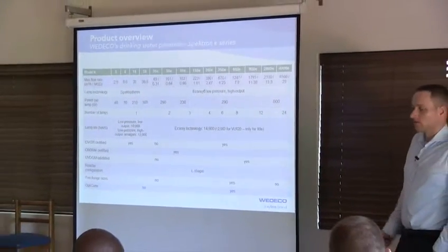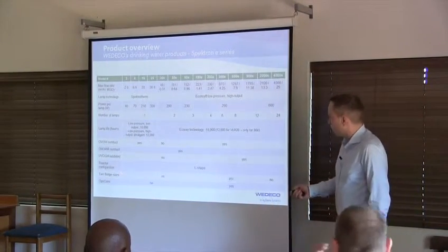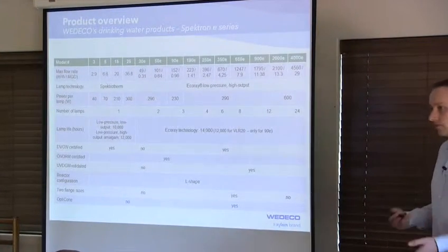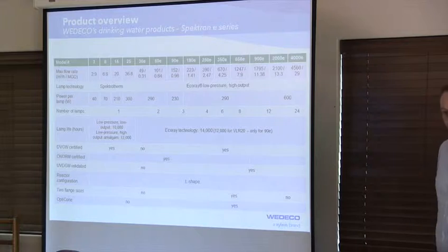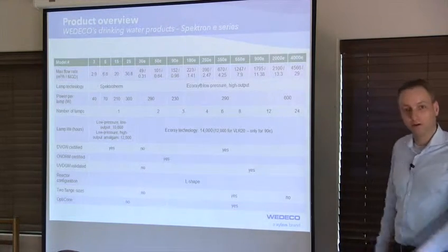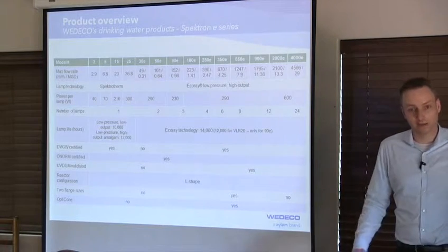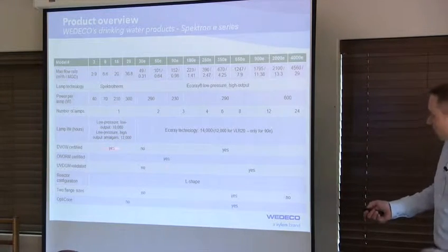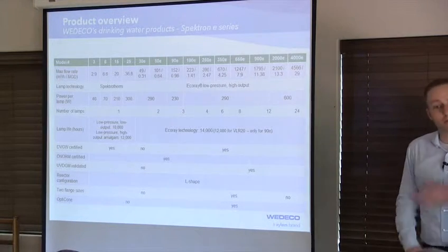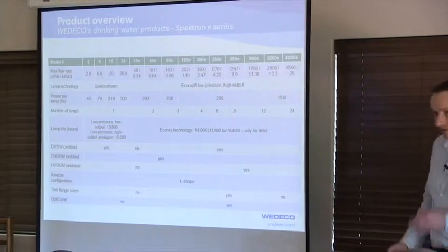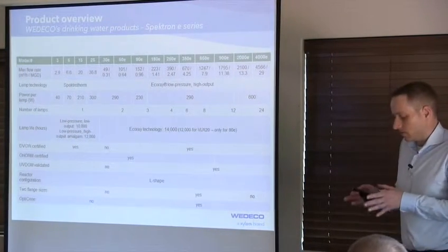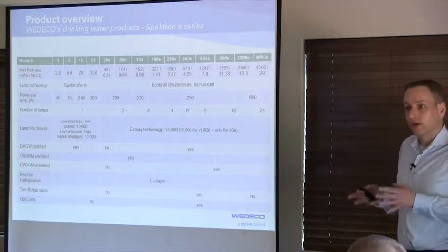Yes. Because the other methods are just calculating the dose from a theoretical base, and there you have a lot of simplifications, like you don't consider the flow pattern inside the reactor, etc. But as these are based on actual biological tests, you know the real performance of your unit, and it gives you a much better overview of what your system can actually do.